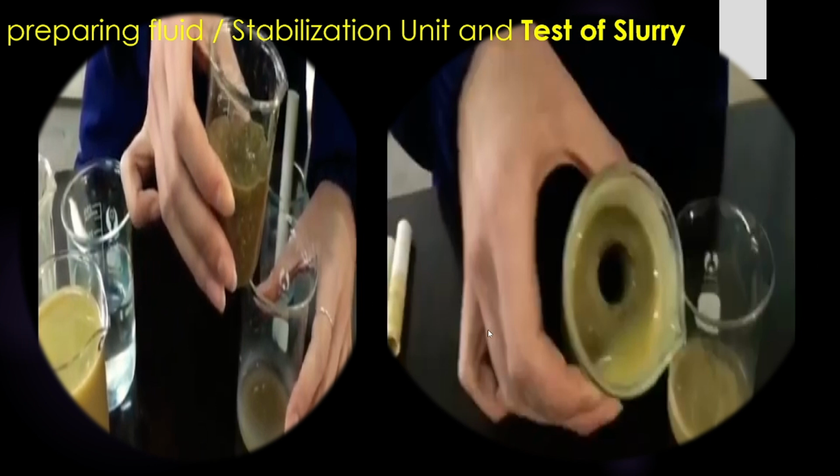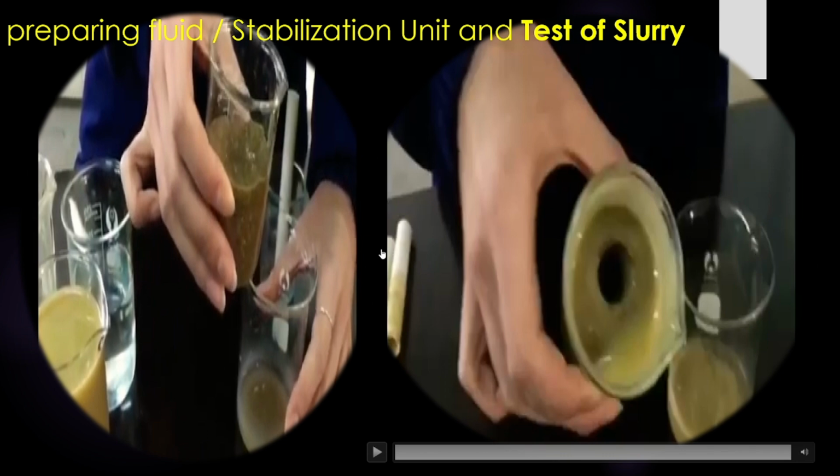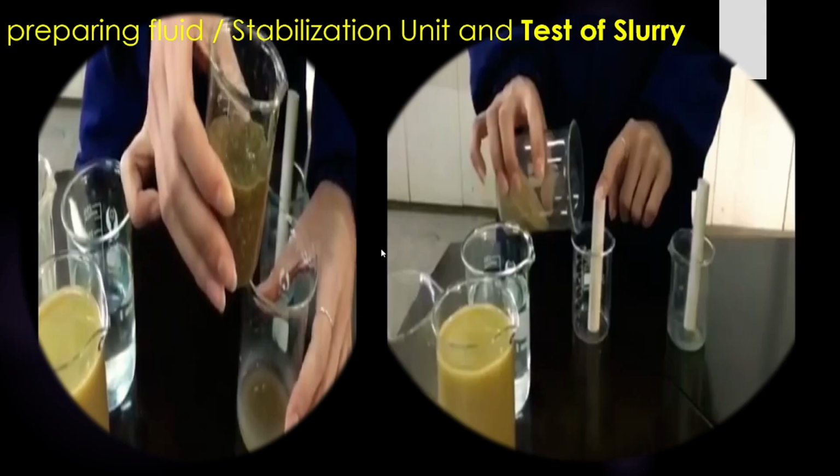Saying this, what you need to remember is that the ingredient that we are going to use is bentonite, which is a fine-grained clay primarily composed of montmorillonite. There are two types commonly used, the sodium-based and the calcium-based, but the sodium-based bentonite is essential for soil stabilization in the piling work. When mixed with water, it forms a slurry so that it stabilizes the sides of the pile borehole.